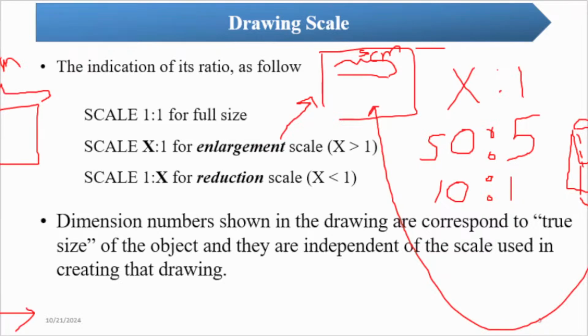If we convert to centimeters, 5 meters is 500 centimeters. Then it is 1 to 100. Scale is something like this. Right? So that is the example for the reduction. We draw large objects smaller, and mention the scale.